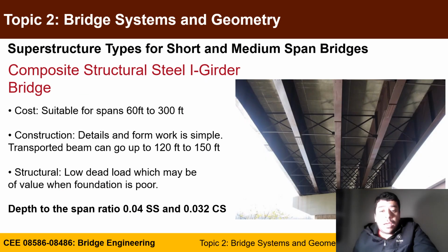The same information is presented here, but with one additional photo you can see here. During construction, when you place the girders, you have to brace them together. The reason is to provide lateral support and stability to the girder to prevent it from failing during construction under lateral loads such as winds. Those girders sometimes, in larger spans, reach 7 or 8 feet depth and provide a large area for wind loading that can overturn the girder. So you always have to use those bracing to connect girders together.